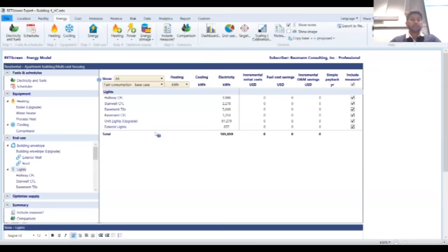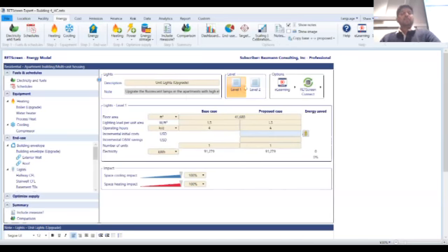to LED. Now, in our model, we went ahead with a level 1 analysis, which is a watt per square feet, or LPD, method, where you have the square footage of the area being served by these lights. You have a watt per square feet value, which is 1.5 in our base case. And we have the number of hours that the lights are on for those units.